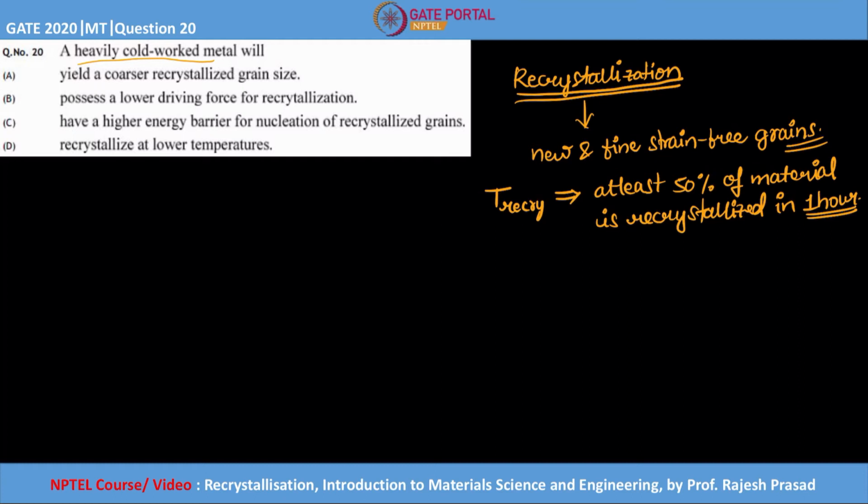And what is the driving force? So we are slowly trying to understand different things. The first thing is the recrystallization temperature, and the second is the driving force. What is the driving force of recrystallization? Here I clearly used the words strain free grains. That means the material is strained, and we want to remove the excess strain energy present in the material, which might come from cold working, hot working, or any deformation.